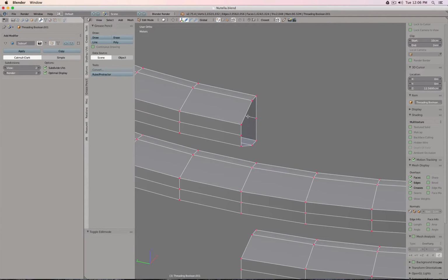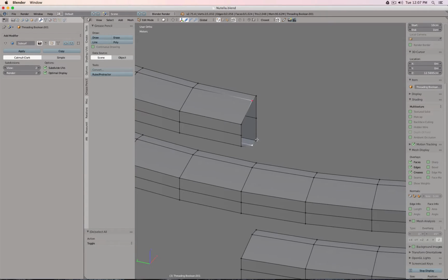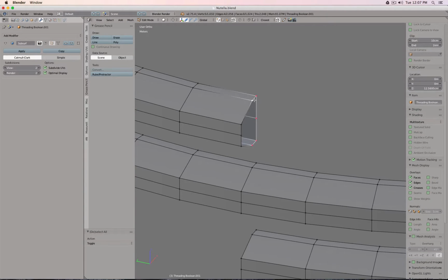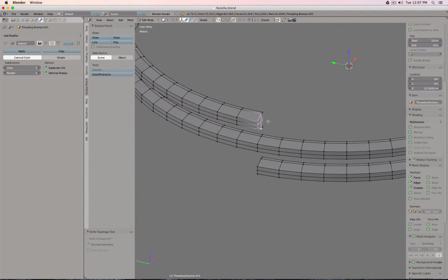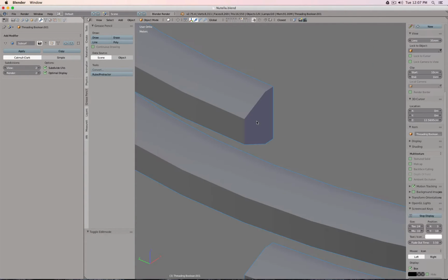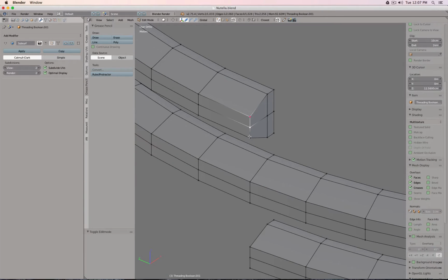So now I can, for example, say F, fill, fill. Actually, K, click, control, click, and click. I make a cut there in between. You will see later maybe why. And then I can select these points, press GG, and now you should memorize the value here with the slider where my mouse is. So maybe I do -0.5.